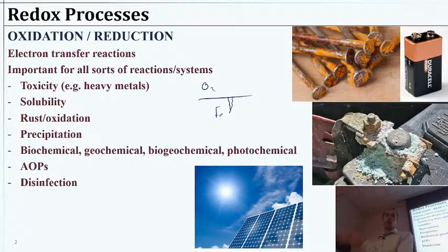There are other cases where, let's say, aluminum, if you have metallic aluminum, it's very difficult to cause it to rust. In fact, it doesn't rust. The reason is that aluminum oxide takes up more volume, more space than base aluminum. So what ends up happening is you do have a very strong reaction to form aluminum oxides, but then it crowds out the space and passivates the surface. Nothing else can grow there, no oxygen can get deeper than that. So all the zero valent, as we call it, aluminum stays in that state, protected by that passivation layer.